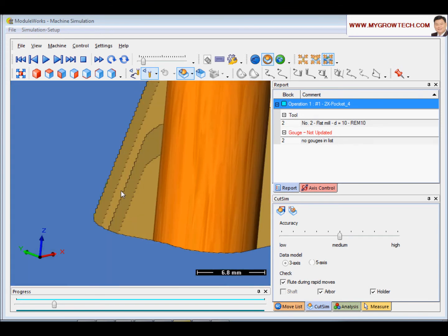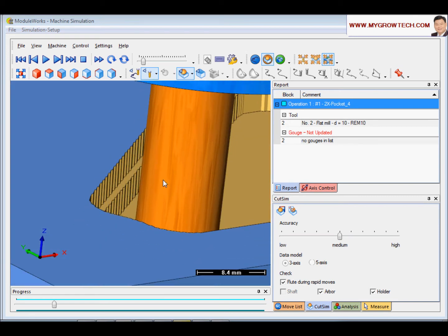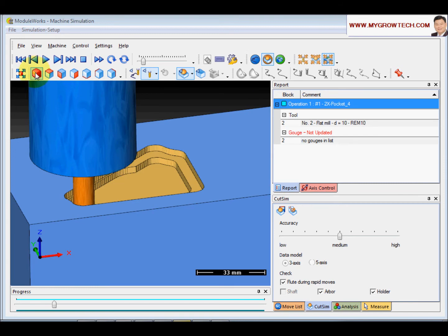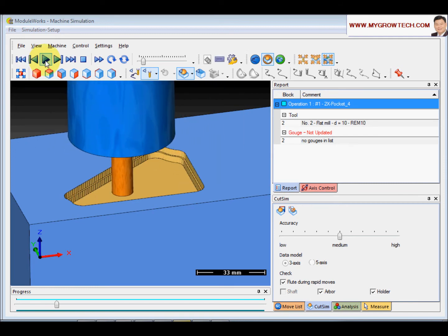This is the contour offset rough. The purpose is to avoid the cutter contacting the wall during roughing. After the roughing process finishes, it will go and cut the 1 mm again.